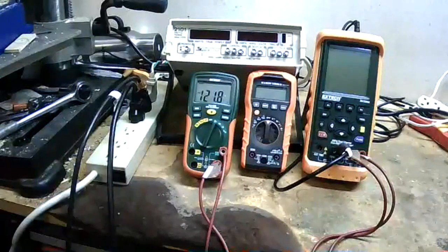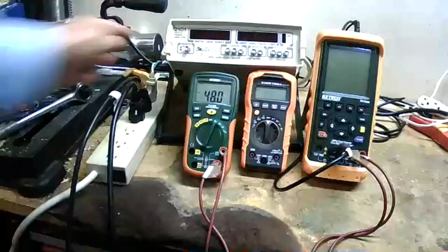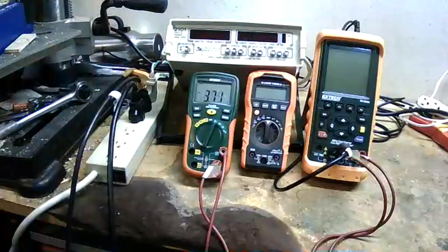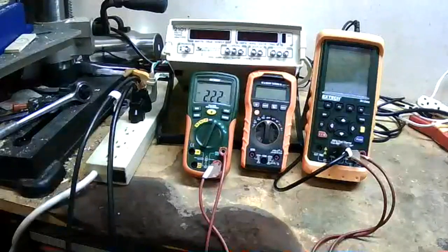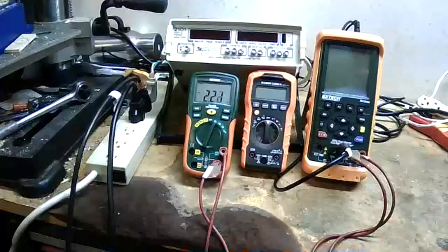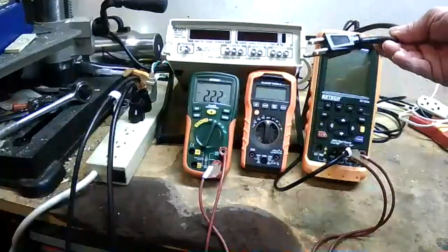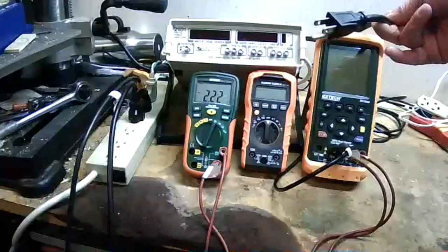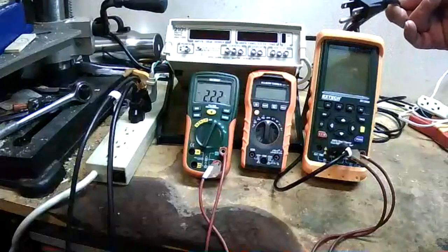I won't work on a circuit when it's energized, so I'll turn the outlet strip back off, and I have actually checked those leads, checked the outlet strip, made sure everything is wired correctly so that when my voltage reads almost 0, 2.2, it is actually off. I'll connect to the outlet strip. I'll connect the plug for my drill press, so it's not working yet.